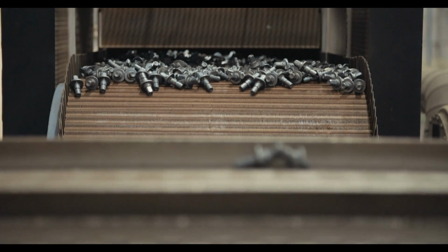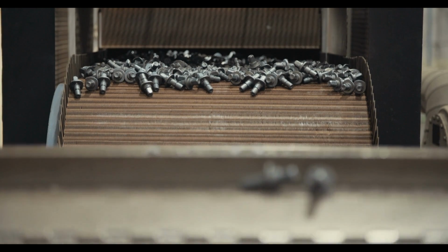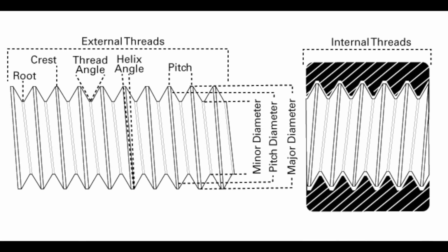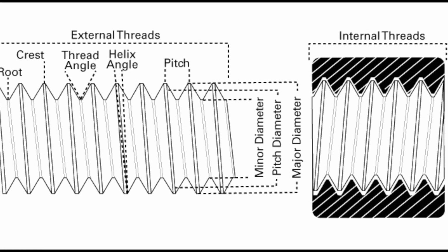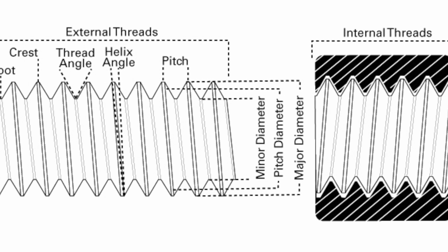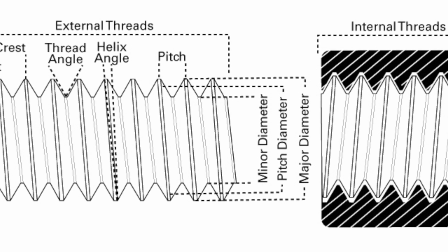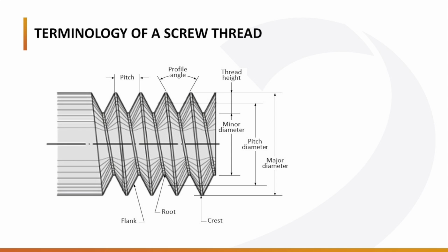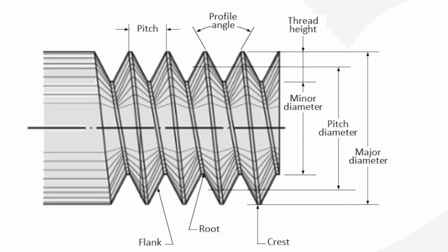So you may be asking, what's the difference between a fine thread and a coarse thread? Well, bolts with a coarse thread have a larger pitch, fewer threads per inch, compared to fine threads. A coarse threaded bolt is specified for most applications unless there's an overriding reason to use a fine threaded bolt. Furthermore, fine thread fasteners are more difficult to obtain. Fine threads are more susceptible to galling than coarse threads. They need longer thread engagements, and they're more prone to damage and thread fouling. They are also less suitable for high-speed assembly since they are more likely to seize up when being tightened.